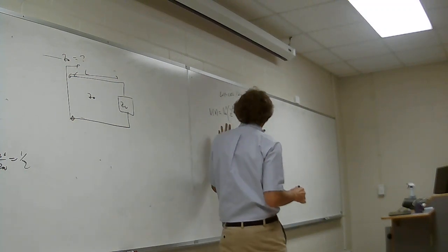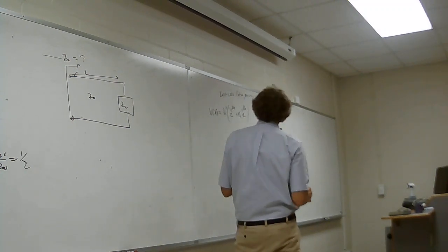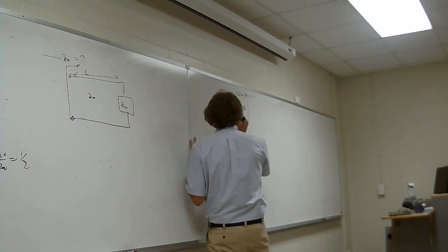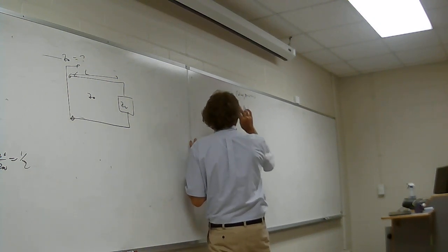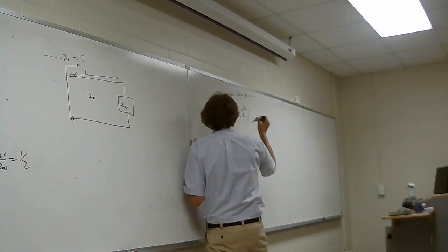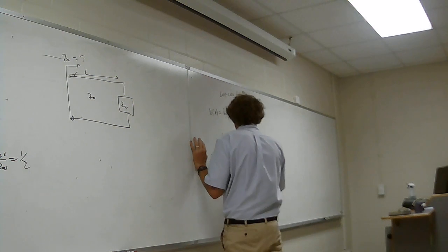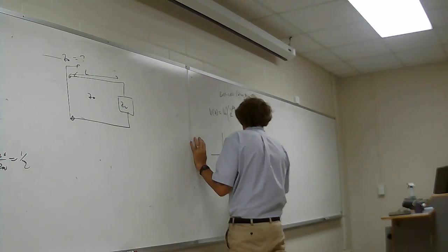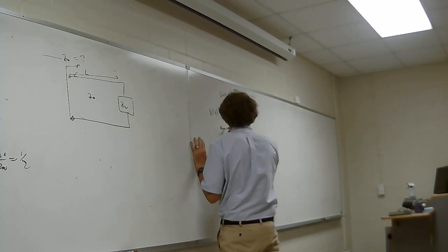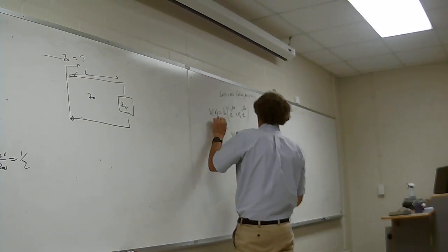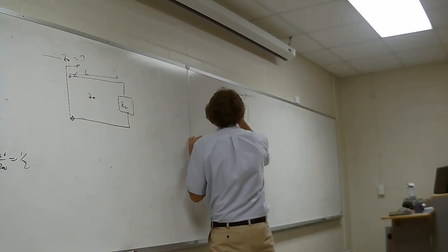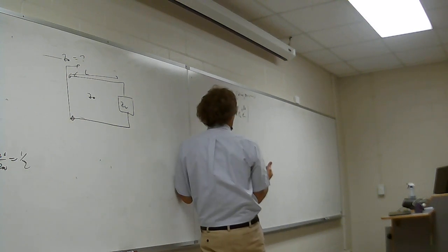Now I want to do this in a rational sense. You take one look at that. If you were plotting that versus z, you basically have V0 here, and you have two vectors. One is moving in the counterclockwise direction, and this is moving in the clockwise direction. So if this is the real axis, and this is the imaginary axis, and you were to plot V as a function of z, take a look at the first term. It's going to have a magnitude of V0, at some angle, e to the minus j beta z.